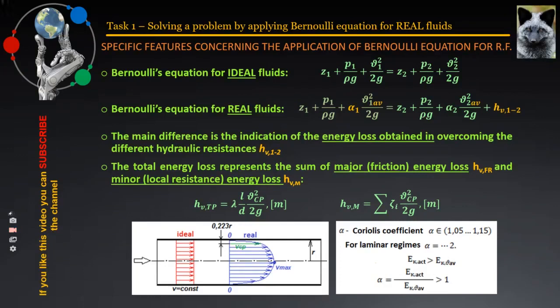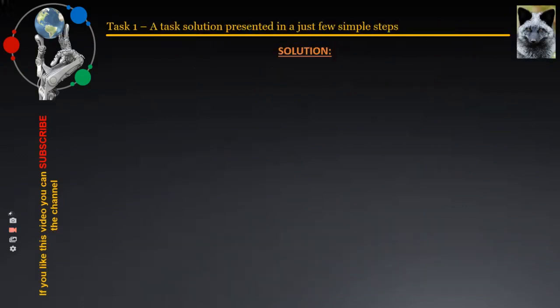The first step, known parameters, in this case involves performing two actions. The first of which is to establish a relationship between velocity and flow rate. For this aim, the continuity equation is used. This will allow us to calculate the average velocity of the fluid flow passing through the pipe, since the flow rate is preliminarily known.